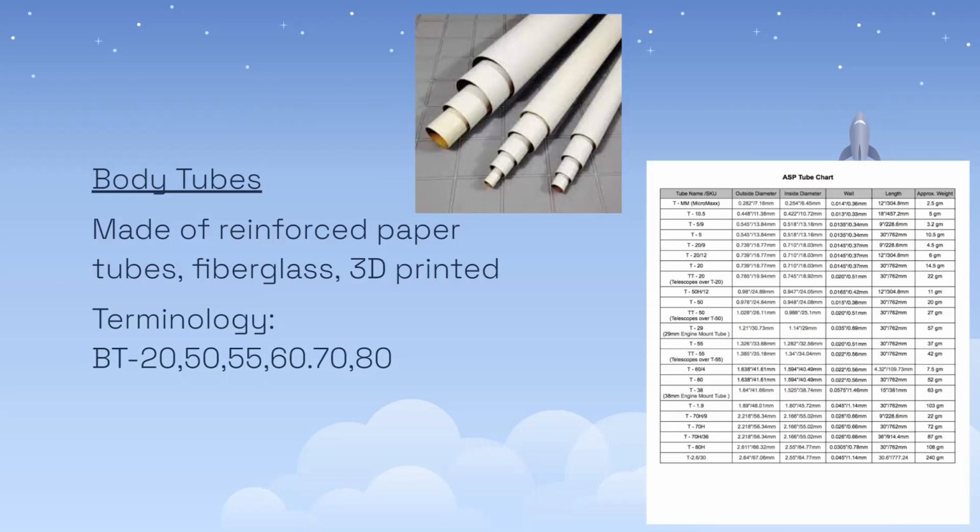Fiberglass is typically used for high power rocketry because of the massive amount of forces that are usually involved with that kind of power. And fiberglass is a lot stronger than paper because it doesn't crumple like paper does. But fiberglass is more difficult to work with. It requires special equipment since you can't just cut it with a knife, and it has a tendency to be more expensive as well.